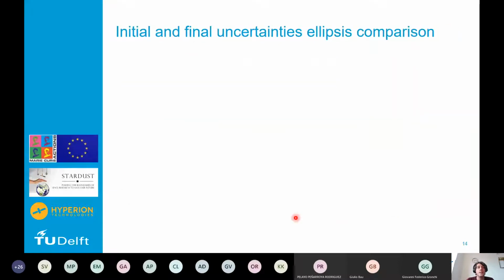The first aspect that has to be taken into account is the uncertainty because of the asteroid ephemeris. Because as you can imagine, if we want a fully autonomous navigation system, a fully autonomous CubeSat, it will not be able to receive updated information on the target asteroid ephemeris. So it will have to rely on the propagated ephemeris stored on board prior to the launch time.